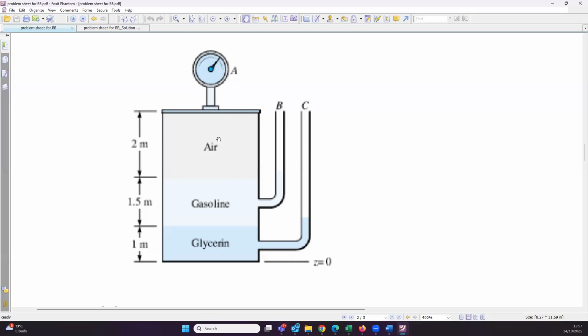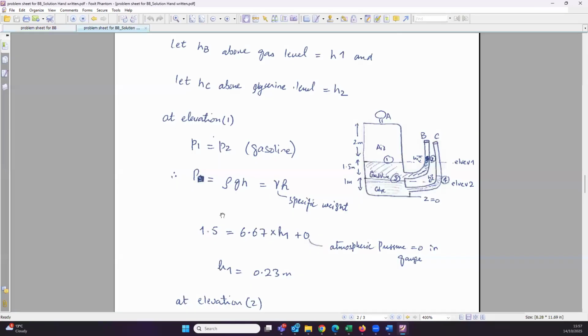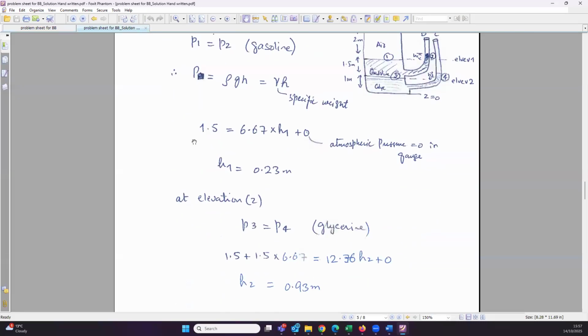The simple tip that I would give you, that if, like in this equation, for example, you have one side in gauge pressure, please make sure that the other side is also in gauge pressure. Because both sides of the equation need to have the same units. Last year, a number of students put this as gauge, while they forgot that the equation has to balance, because they just thought in terms of the units.